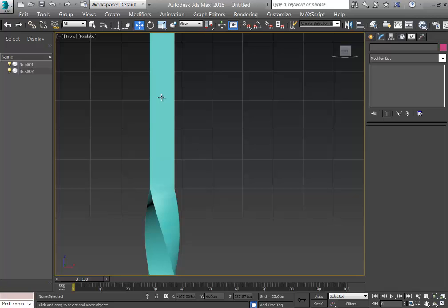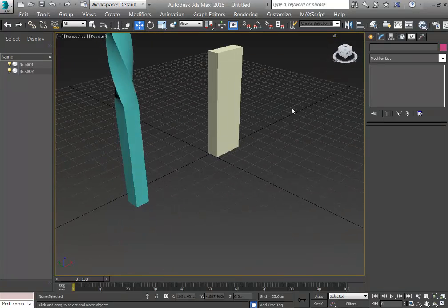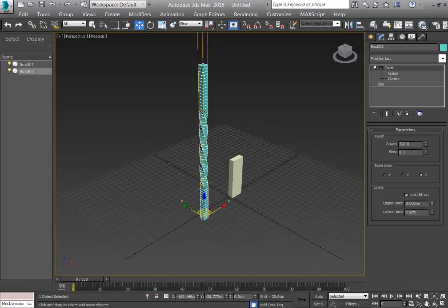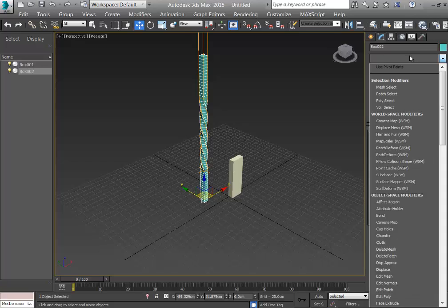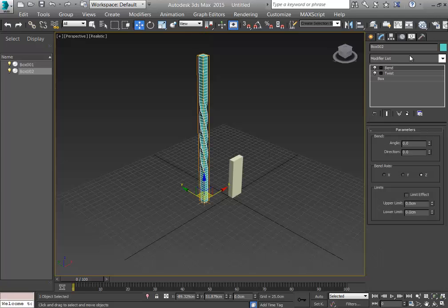Banding is again another modifier which has the same approach. Banding again has the gizmo, and we will apply that on this box. So what I'm going to do is go to the perspective view and get into the original look in here. This is what I have now, so let me make this box banded. After the twist, I'm clicking on this modifier, and I'm writing in here band. So now you see there's another rectangle drawn on my box.